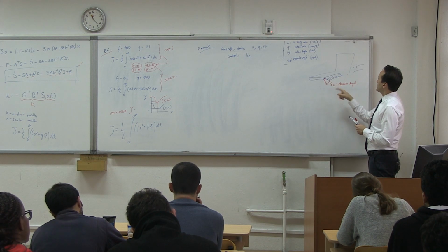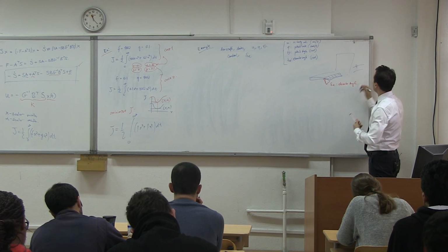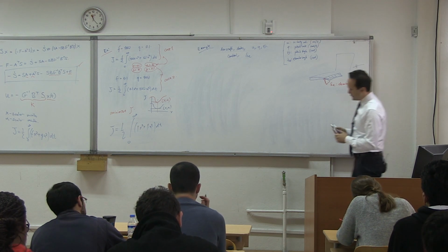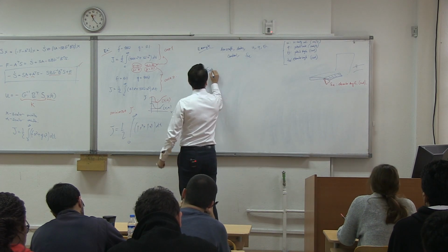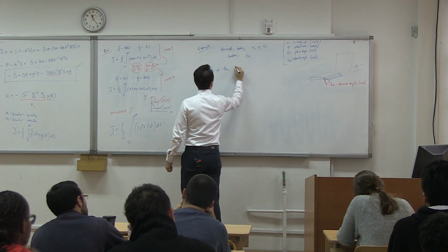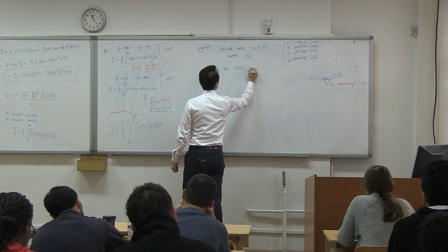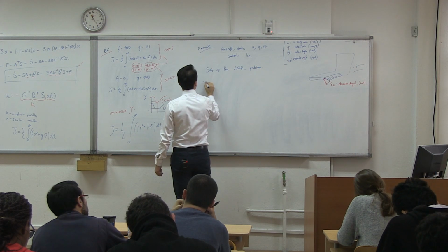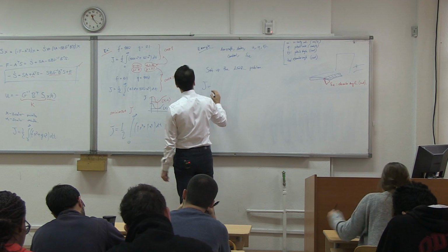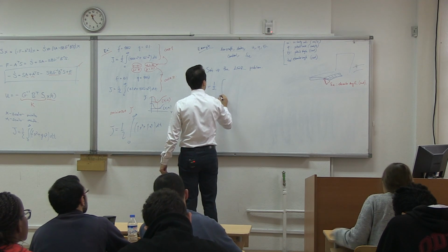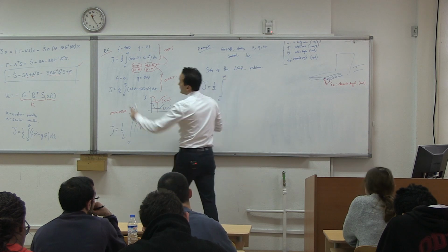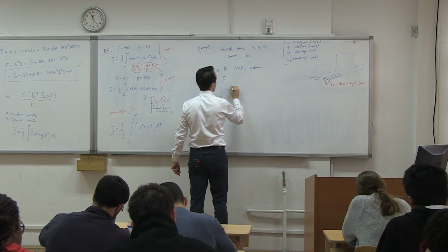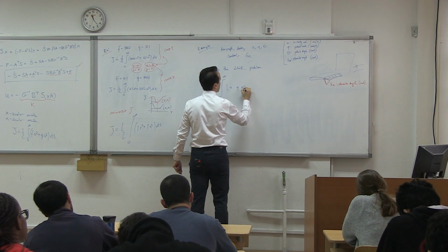So you can move it up and down, and it's the elevator angle, and this is in radians. Okay? So let's set up the LQR problem. So J is going to look like this: 1 over 2, integral from 0 to infinity, x transpose Q x, with x being U, Q, theta.